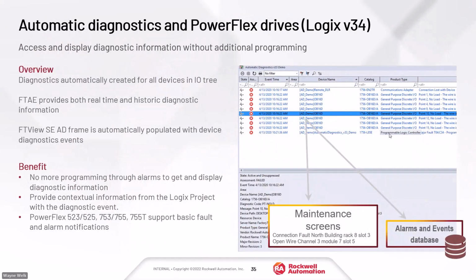So with PowerFlex drives, those of you that know our Logix controllers really well know that automatic diagnostics was introduced to our L8 and our CompactLogix controllers back in version 34. I'm getting over a cold, I have a little bit of a cough, but PowerFlex drives also support automatic diagnostics. So that's kind of the first step. You basically just click a button in the configuration, and it allows all the drive diagnostics to be sent to the HMI system through FactoryTalk alarm events. So go ahead and go to the next slide.